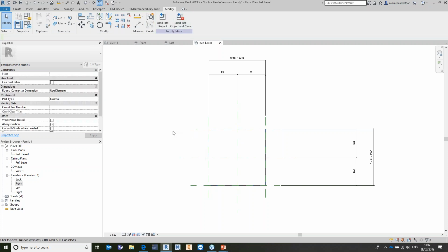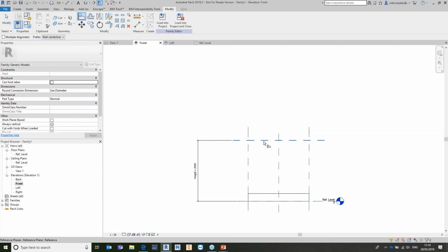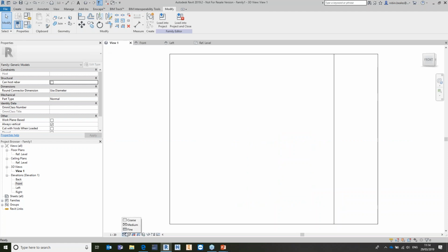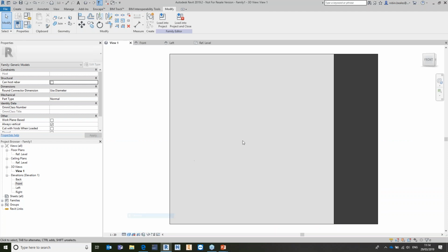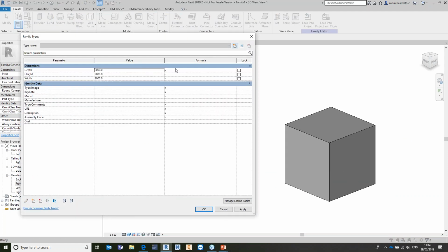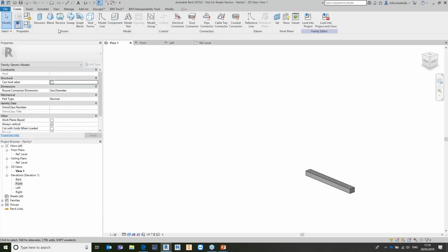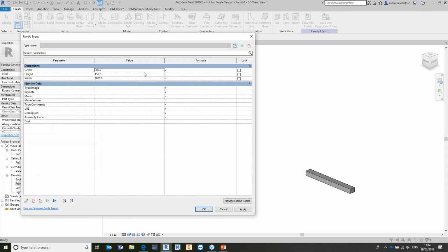What this means now is when I press the big green tick, I basically have a box. I'm just going to link that box to my height and lock it. Head over into a 3D view, turn on a slightly different view so I can see my box here, and show you that we've created a fully parametric box in a matter of seconds. So we can come in and drive any element on here, no issues. It's a parametric component. The key, if I wanted to start making that into a BIM object, is to make sure that you're matching the level of detail required against that object.